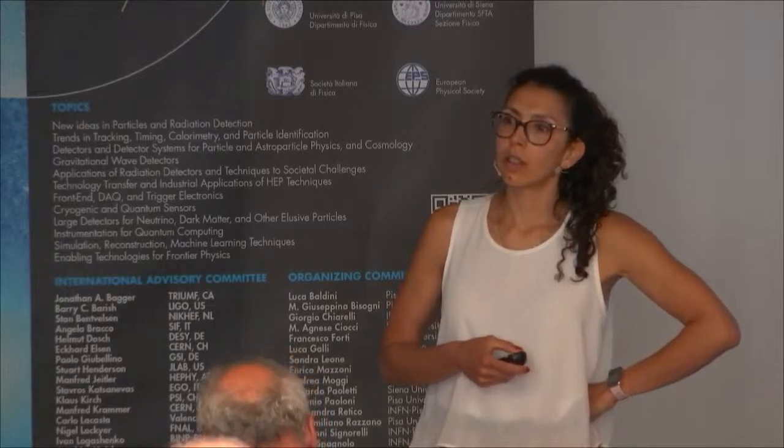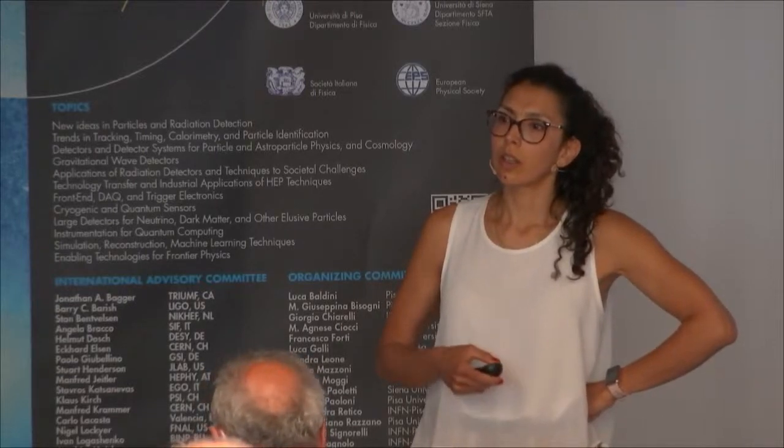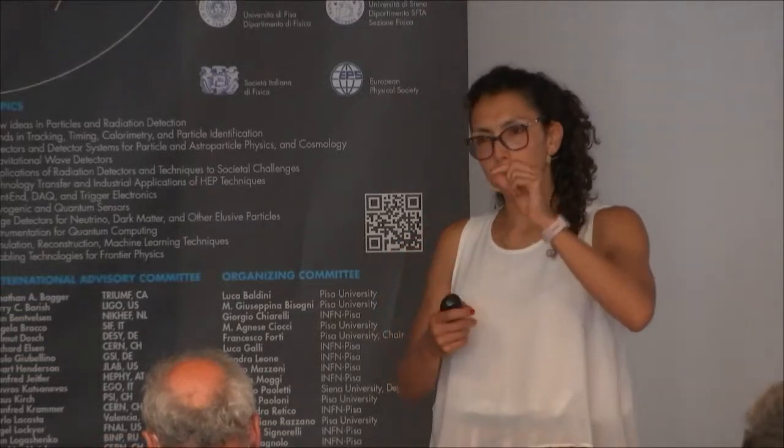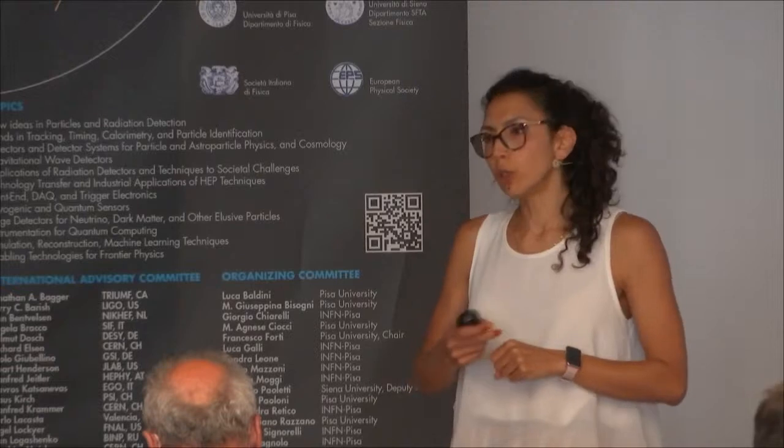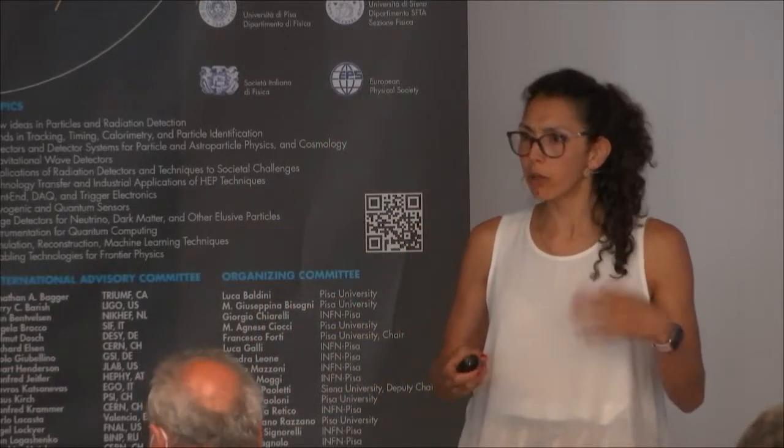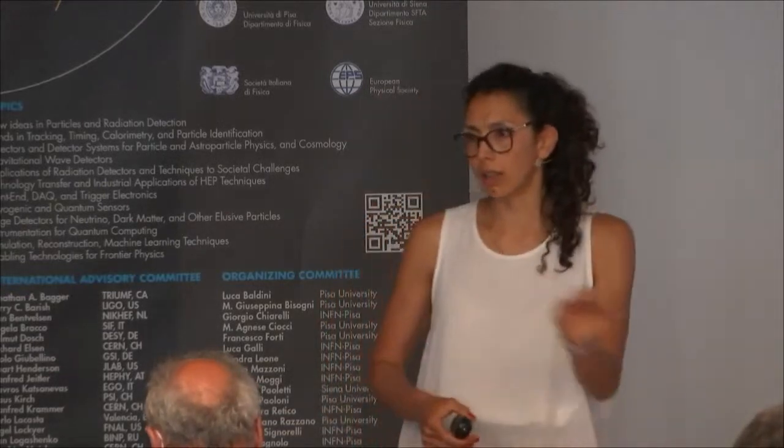And finally, all the photomultipliers are read out by the last line, right? Yes, all of them. But this is AC coupled, so isn't the baseline fluctuating? No, not really. It's really stable. This is the PCB on which the photomultiplier is placed. It was developed by the INFN division of Bologna, and they performed a lot of studies on where we were taking the signal, and it's really stable.